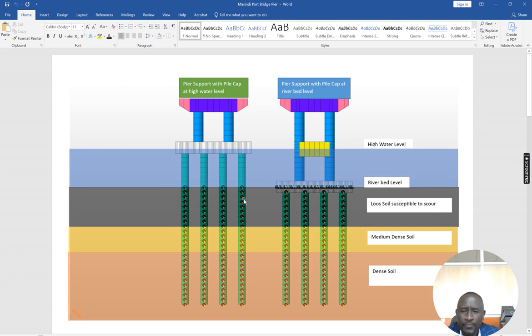While here you have a portion of pile in water. By the way, this pile length is about 24 meters. So even here was about 24. So it will slightly be up here, but because of the rock quality at this elevation, it was bearing in rock of less quality than down here.